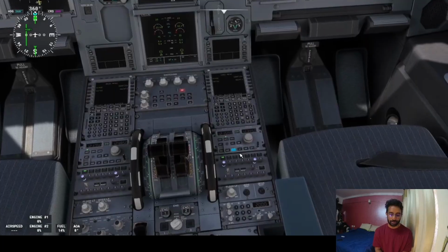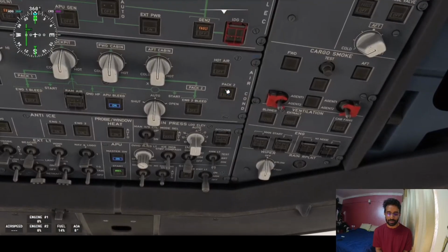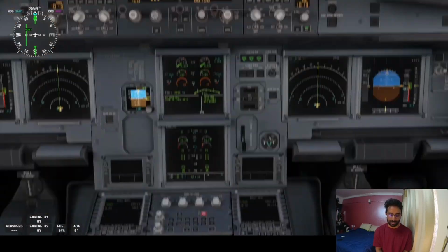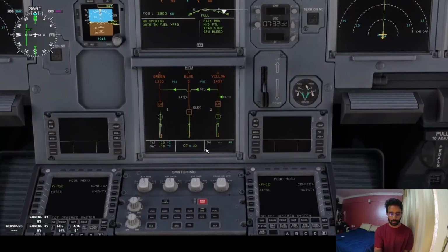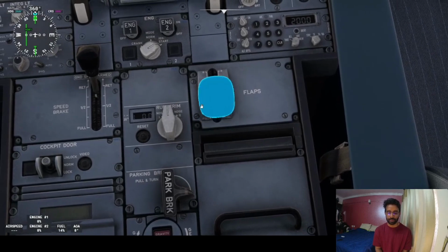Okay. This time, you park the aircraft, flaps are at full. And then you tell the ground staff, see, I want to pressurize the yellow system. You got the clearance. Put the yellow pump on. The yellow pump will pressurize the yellow system. The PTO will pressurize the green system. Now you put flaps to 0. So what did you do?